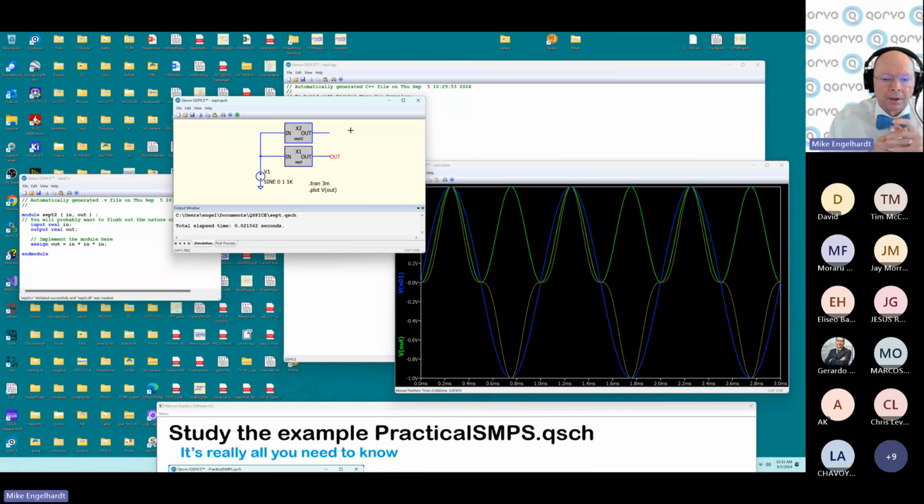You don't have to write it. And the third reason is you're designing an IC, and once you've got the Verilog, you want to synthesize silicon against your source code. So you might actually want to design the IC. Those are 3 good reasons for using Verilog. But unless you fit squarely in one of those 3 reasons, I would recommend going to C++. The problem with Verilog is that the Verilog supported in QSPICE is called synthesizable Verilog, which is a polite way of saying you can't use a delay statement.